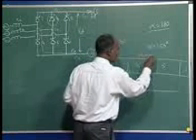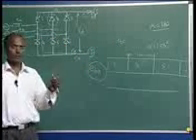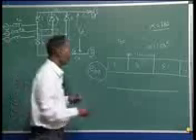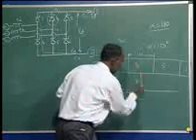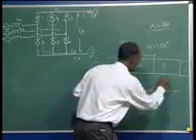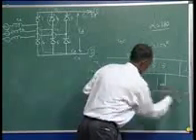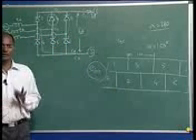This 120 degrees means each valve in the upper limb is conducting for 120 degrees. However, the pairs were conducting for 60 degrees. Now here this is 2, here it is 4, here it is 6, and again 6, and so on and so forth. So this was the ideal case.